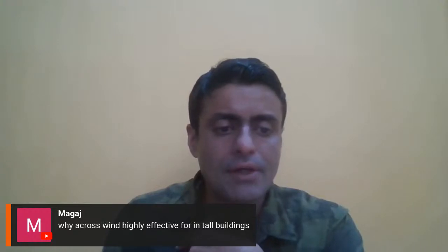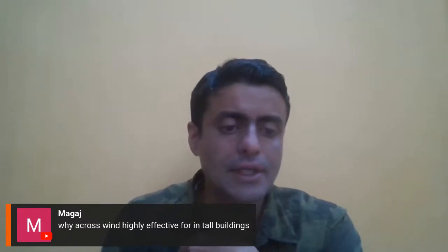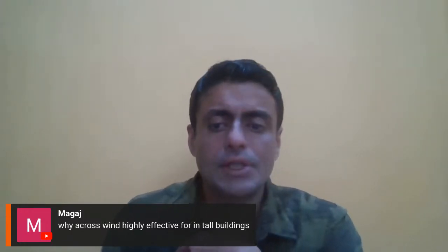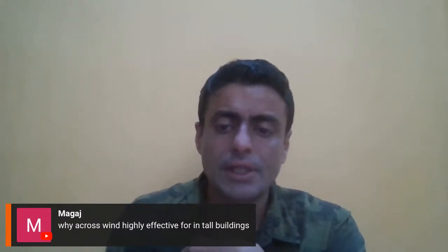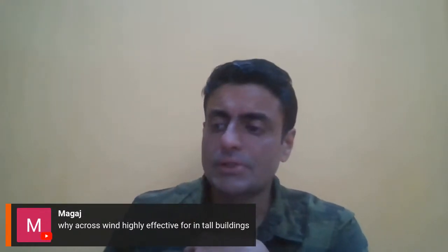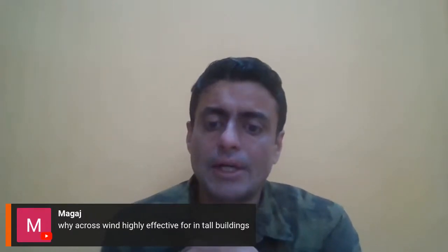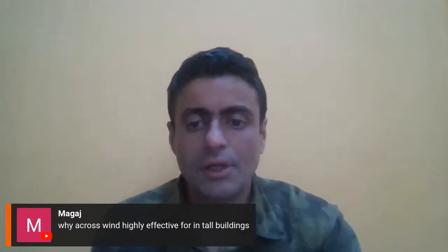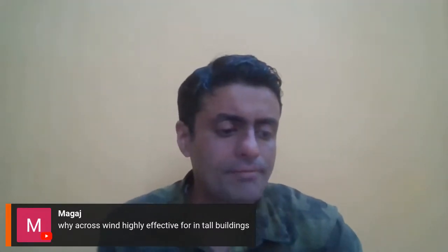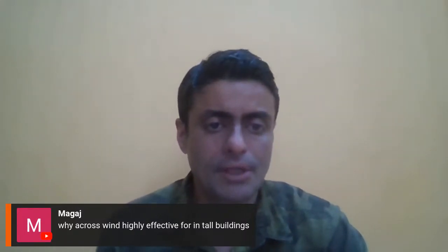Mr. Magaj is saying why across wind is highly effective in tall buildings. It's not highly effective. You should have said why across wind response is highly critical in tall buildings. The reason is because of the vortex shedding effect that takes place. You might get the across wind responses which may be governing, but remember that those are governing for slenderness ratio of your structure going beyond 10, more than 11, then the across wind response becomes critical.